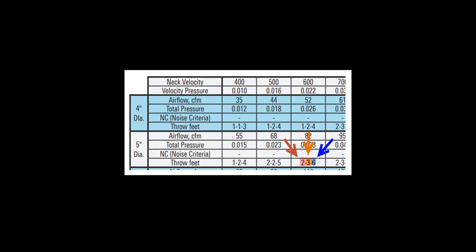Always check at the end of the table for the performance notes, because typically manufacturers will publish this in isothermal conditions, meaning the supply air is the same as the room temperature, but sometimes they could publish with a heating or a cooling value instead. Also, typically they are referenced to a testing standard, ASHRAE 70 of a particular year. You always want to make sure that you're looking apples to apples to make sure that you have isothermal conditions or ASHRAE standard 70 matching for different manufacturers.